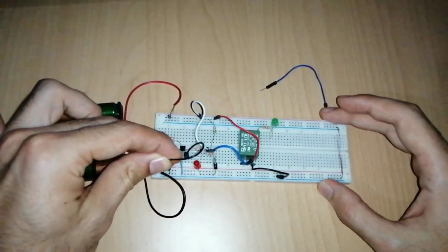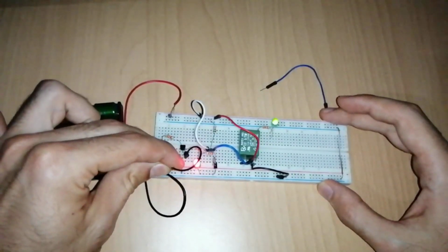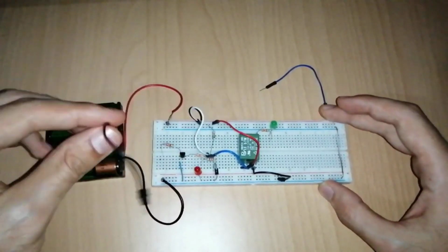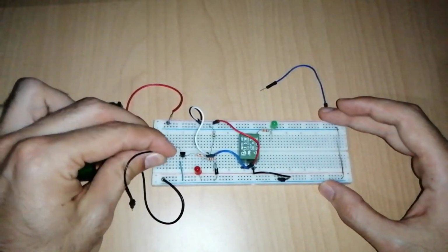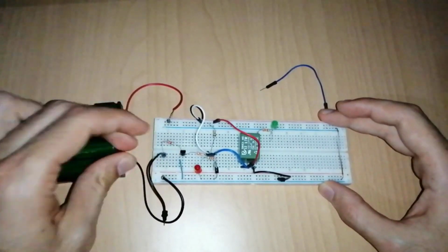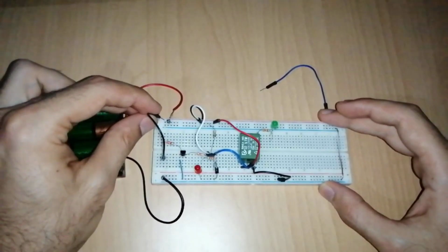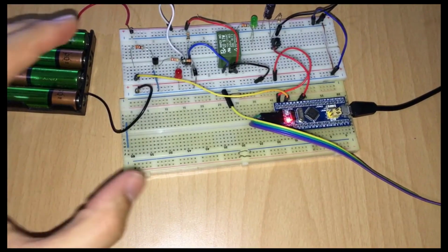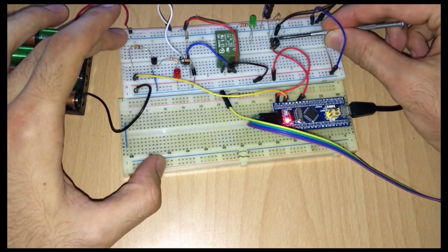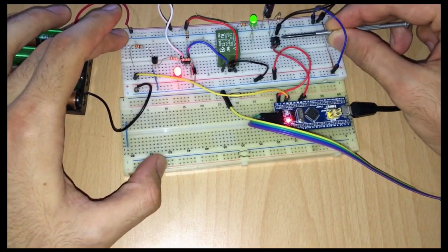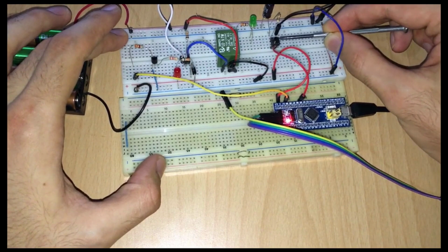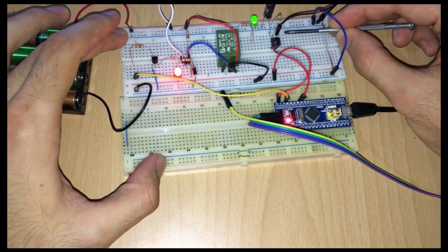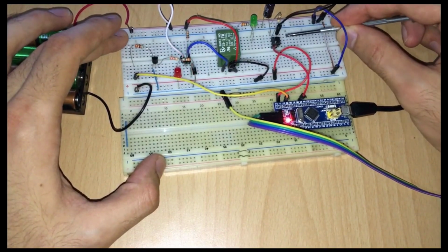Having completed the theoretical part, let's do something practical. Here I have constructed the circuit I have discussed to test the functionality of active low and active high feature of the driver. After that, I've used STM32 microcontroller to control the relay driver by generating an interrupt that changes B9 GPIO pin state when a falling edge at B5 pin is detected. And here's the result.